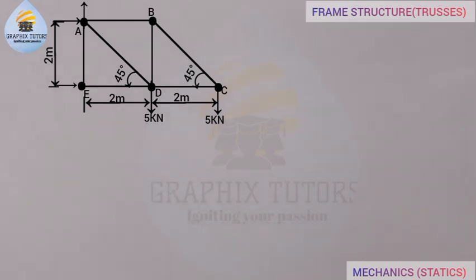So we'll call this reaction acting upward our RAY, meaning reaction at point A along y-axis. We'll call this our RAX, meaning reaction at A along x-axis. We'll call this our REX, meaning reaction at point E along x-axis, right? So that's what we have.